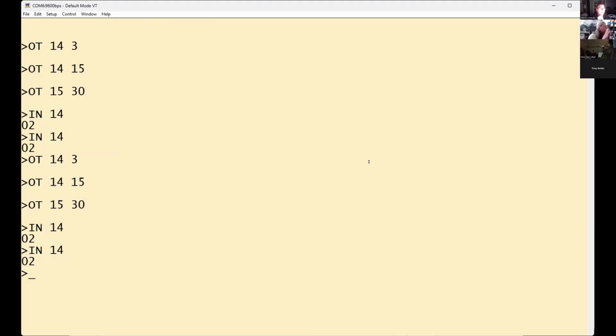So that's what I'm saying. Even without typing something, the UART on your 2SIO is not seeing the characters you're typing on your Tera Term. The received data comes into your 2SIO, it runs through your line converter, it hits the 6850, it sees the character, and it sets the received data bit. And it's not even doing that. So either the IN 14 we're not getting that 2 from the 2SIO and we're just by chance getting a 2, or there's something else going on.